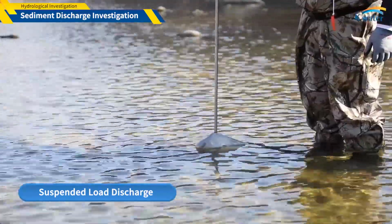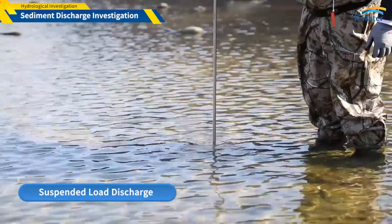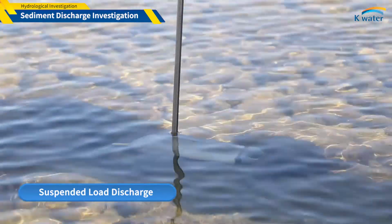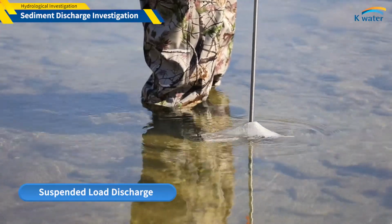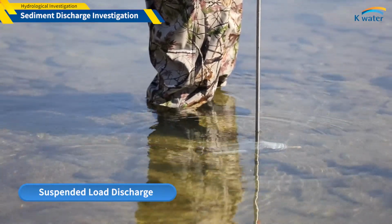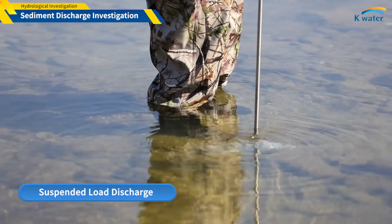If the water is shallow and the flow rate is slow, the operator can directly enter the river to measure. If the water depth is 4.6 meters or less and the flow rate is fast, a depth integrator should be used. When the depth is more than 4.6 meters and the flow rate is fast, a point integrator is used. When flow rate is very fast, the water surface sediment collection method can be applied.